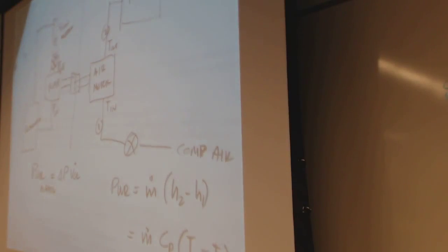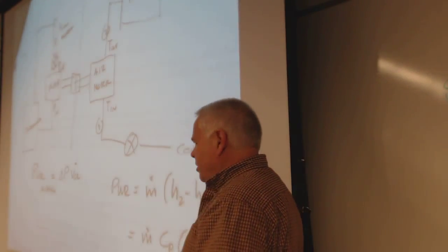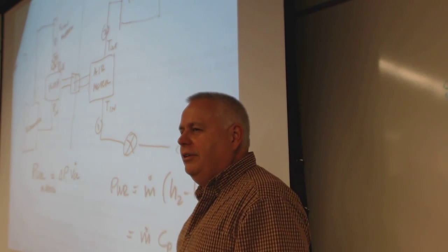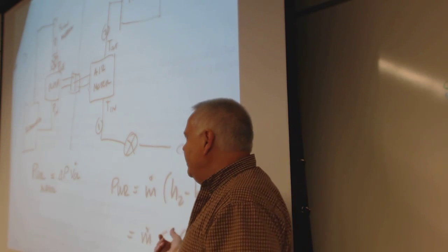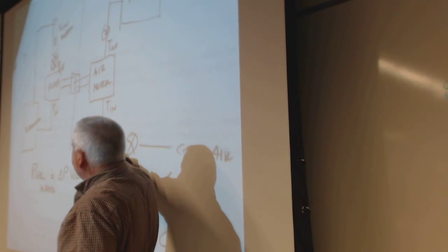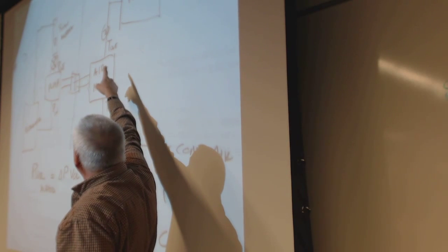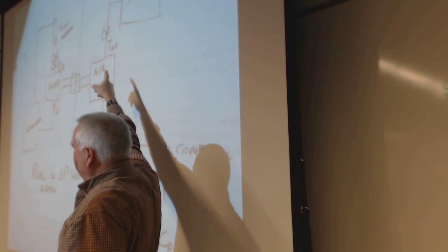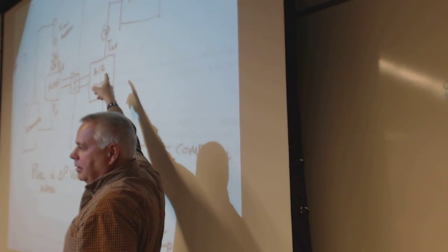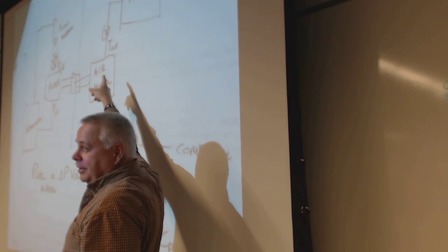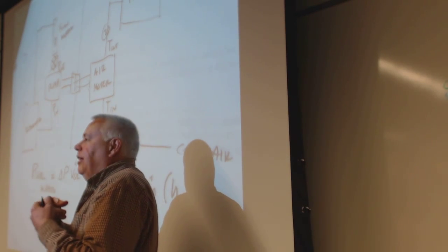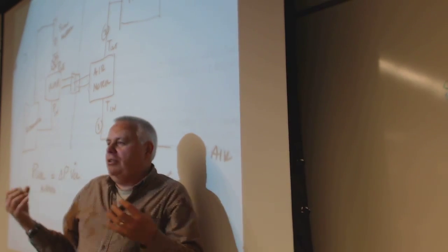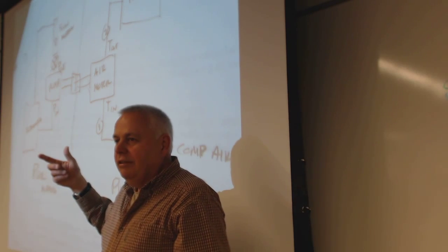What about pressure? We said this will get us there, but we know there's pressures there. What about the pressure? Do we need pressure? If this was at really high pressure and it expands, what's the temperature on the outside? What happens when you expand a gas? Does it heat up? Does it cool down? Yeah. It's cooling down. It actually does work, and the fact that it cools down says that it expended some energy somewhere. It did it in turning the shaft.